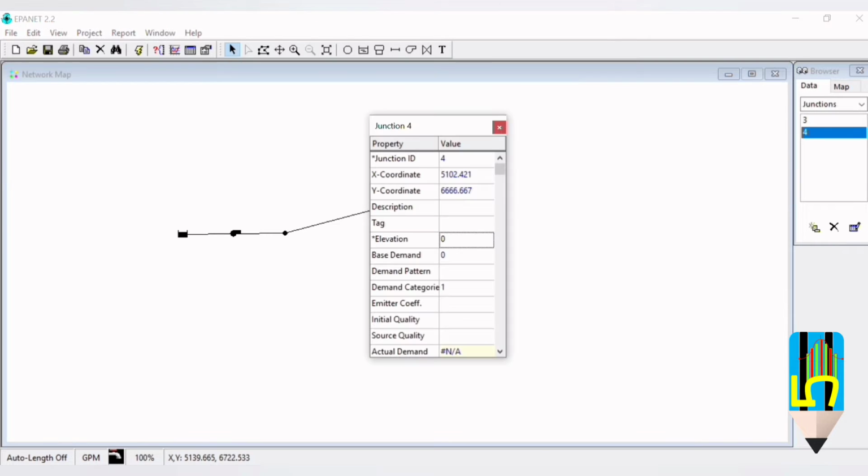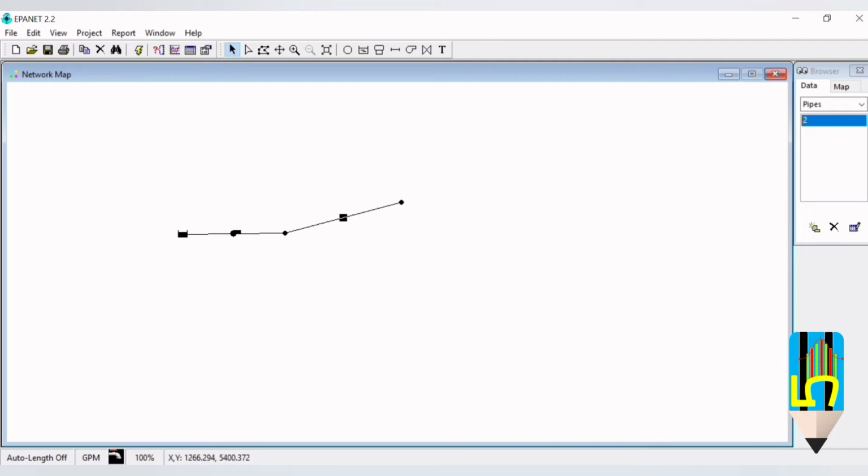And then the third node where the water has to be taken to, this is at an elevation of 260 meters, which is a difference of 250, and the base demand is 1 million liters per day. Then the pipeline, the diameter initially we consider 100, and then the length is 500 meters. So you can see that in 500 meters we are covering a height of approximately 250 meters. So it clearly means that it is a kind of hilly terrain or something.